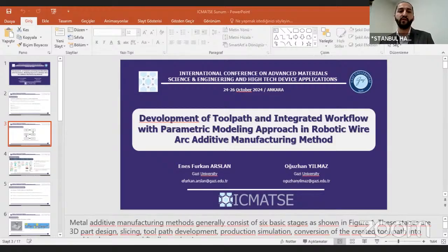And future works. In the study, we used a 2.5D slicing strategy. Thus, future studies plan to develop the workflow for more complex parts with overhanging geometries. Moreover, monitoring the deposition parameters in the process using automatic feedback systems will be the focus of our next and future research.